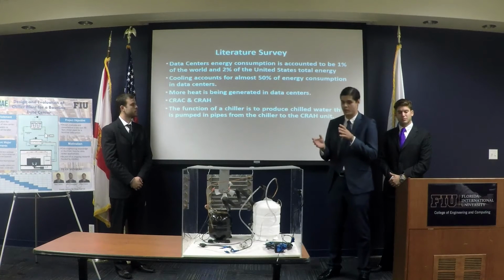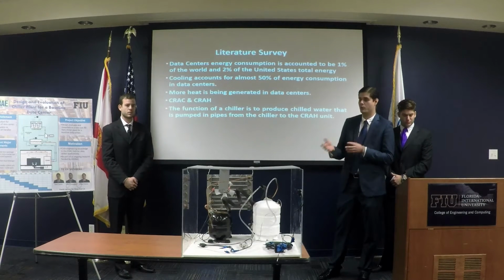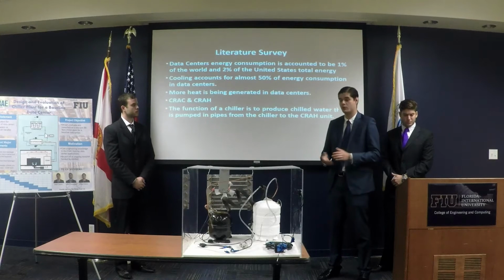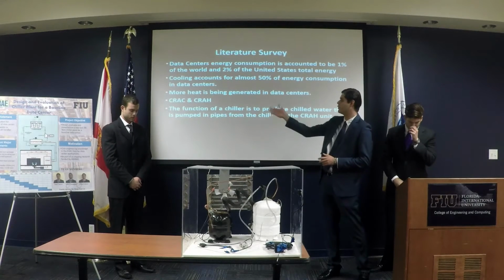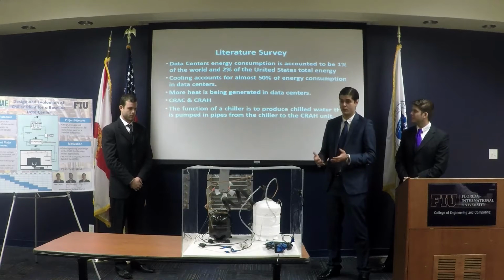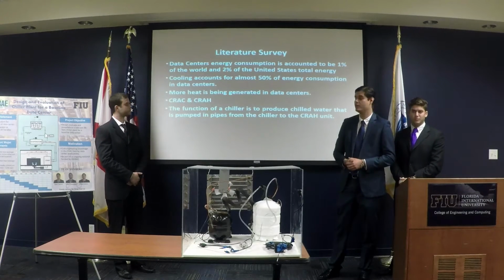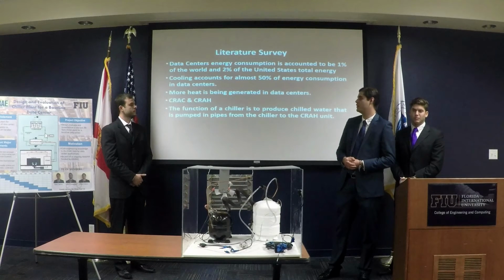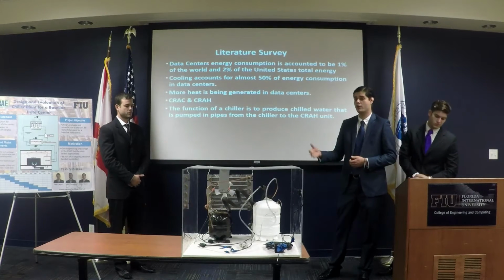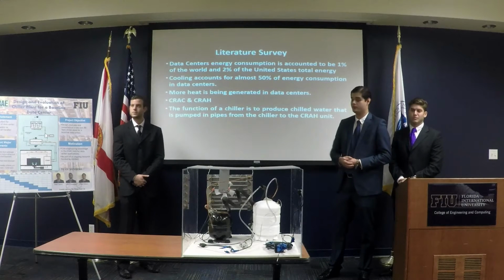Data centers can actually be cooled down by air or water. The air-cooled method is the most widely used. In order to do this, a computer room air handling unit is used, and this unit needs to work in conjunction with a chiller plant. The chiller plant is located outside of the data center and provides cold water constantly to the CRAH unit.